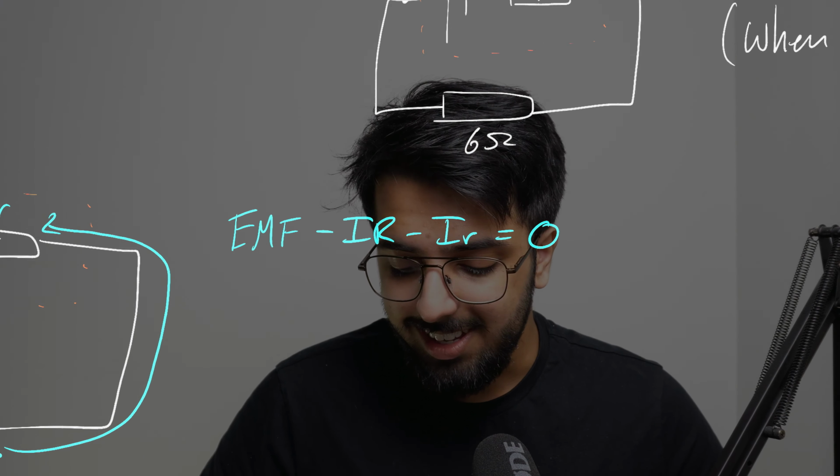Now remember, we're not allowed to measure the voltage across the terminal like this, because that does not include our internal resistance, and therefore it does not accurately model what happens in real life. And so we must include the internal resistance and the power supply when we use a voltmeter, and so the voltmeter has to be on the outsides like that, okay? Has to start here and then end here, okay?